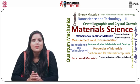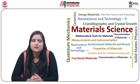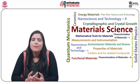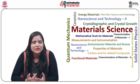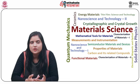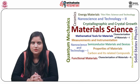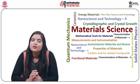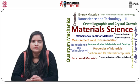Surface and interfacial contamination is the main problem with nanoparticles which are produced by high energy milling. This contamination may be caused by the milling tools, that is, milling balls, or ambient gases, which may be traces of oxygen, nitrogen, or other rare gases present in the environment. Nonetheless, the milling speed and processing time can be optimized to alleviate the problem of contamination.